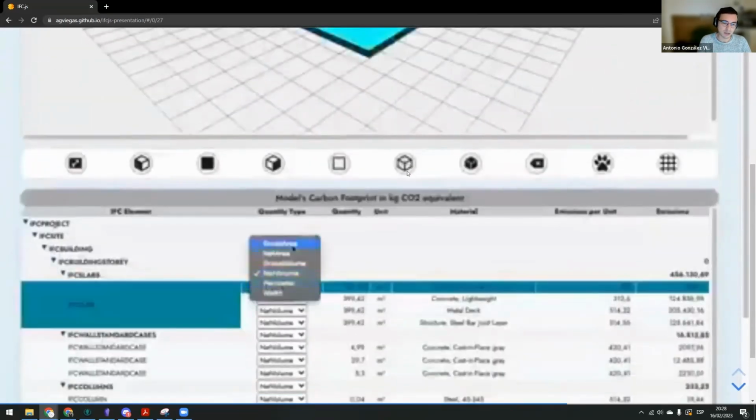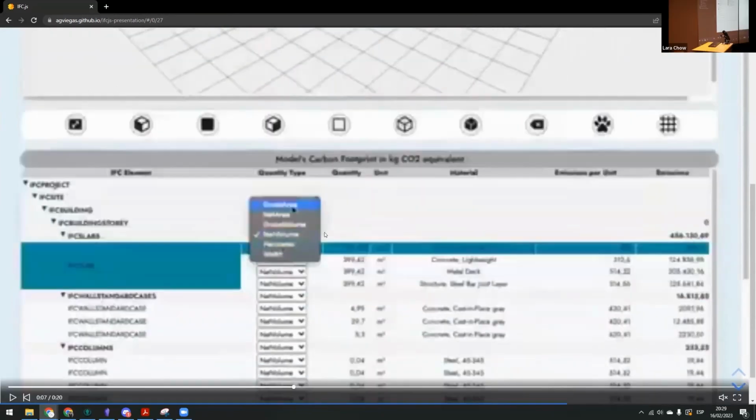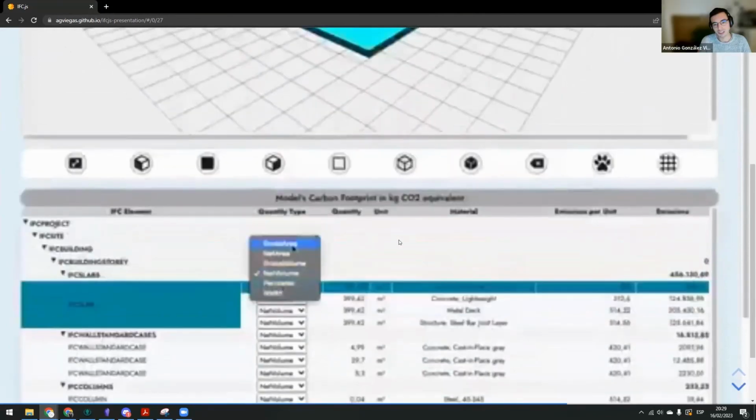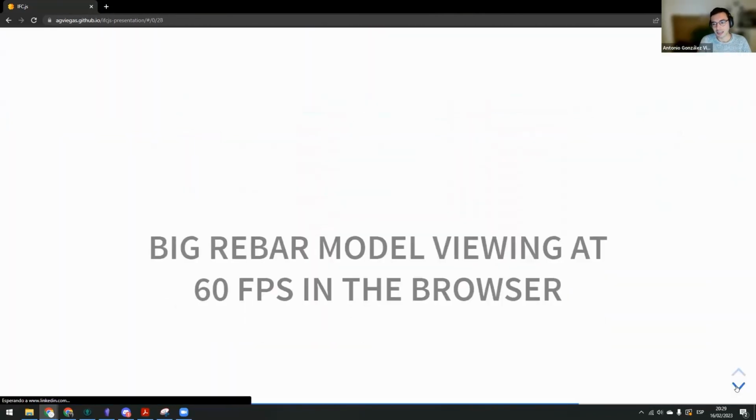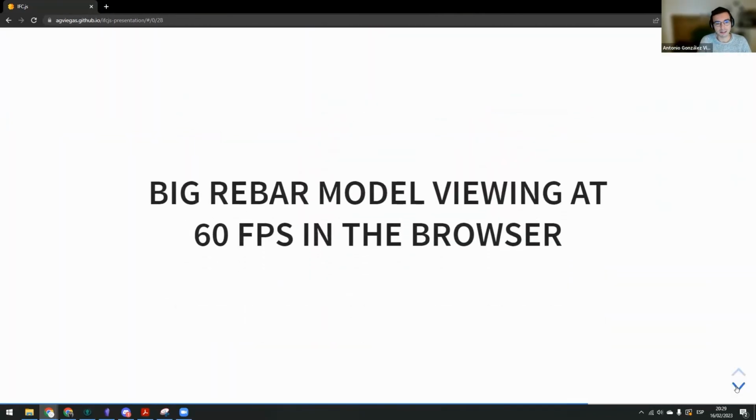They constructed a tool that allows people to load IFCs and set an array of rules to indicate how to measure the elements to extract the quantities of the model. Like, okay, you should measure the walls like this, you should measure the slabs like that. And once you had the set of measures, you could cross this with a price database and get the final price for the building, right?